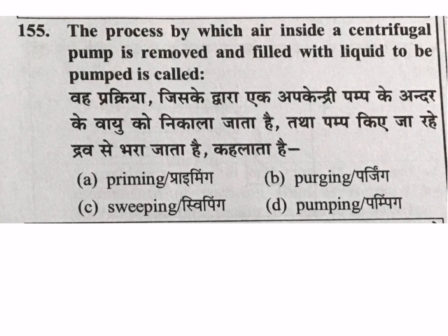Question: the process by which air inside a centrifugal pump is removed and filled with liquid to pump is called as. So we are removing air inside the centrifugal pump and filling it with liquid. This is priming. In our household pump also we used to do that. It may be self priming or you have to do priming by manual methods. You have to fill water, then after priming only the liquid will lift. So the answer is priming.